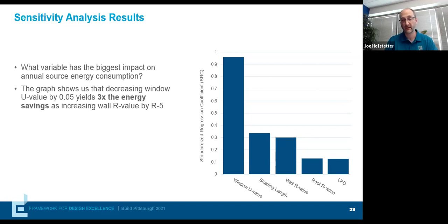So if that's X amount of dollars per square foot that my CM puts out there as your average system, and I have specific energy targets that I'm trying to achieve with these levers, I want to make sure that's X plus a certain percentage, 20% better, 30% better than maybe what my original budget was. And for things like lighting power density, roof R-value or wall R-value, maybe we reduce some value there to try to make up for that, if energy performance is our key item that we're trying to achieve here.